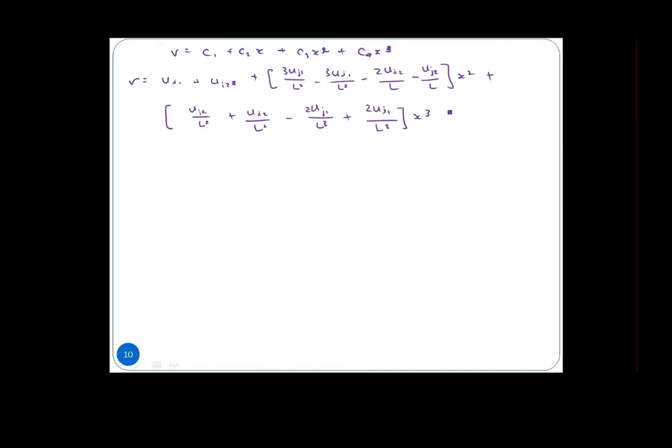All right. So we can rearrange, if you remember, in terms of shape functions, right? So our v itself, we can actually write it in terms of shape functions as si1 ui1 plus si2 ui2 plus sj1 uj1 plus sj2 uj2. We also have a node I, but under one node I, we have 2 degrees of freedom. This is related to vertical displacement. This is related to rotations. Vertical displacement for node J, and rotation for node J. So that is in terms of shape functions.